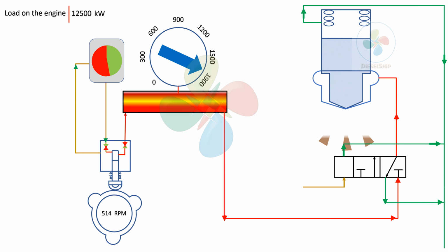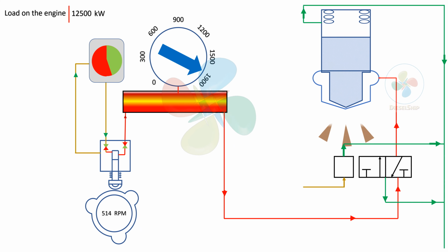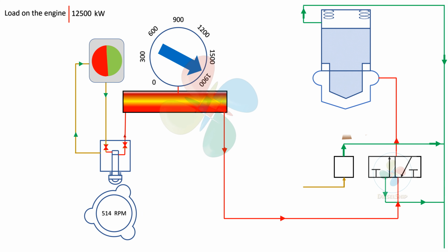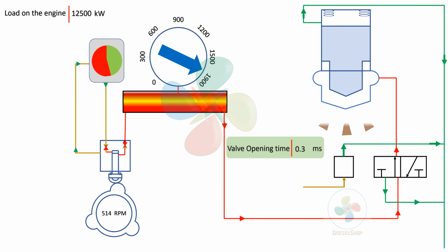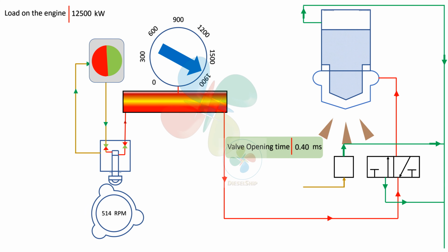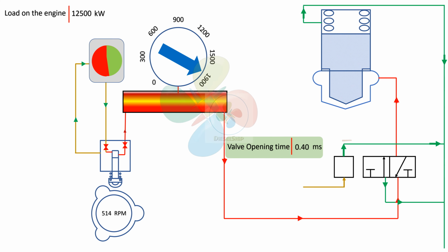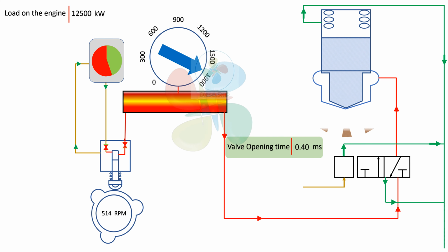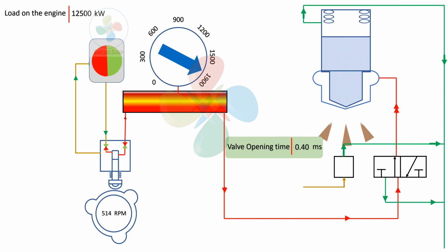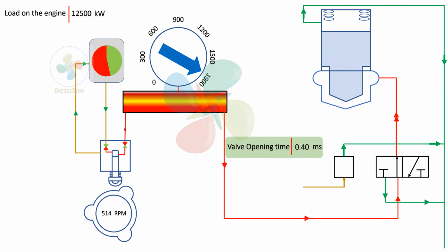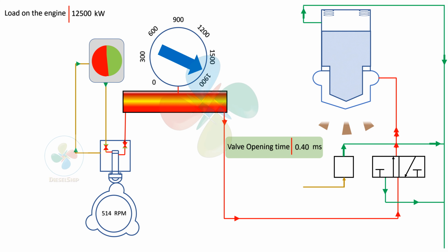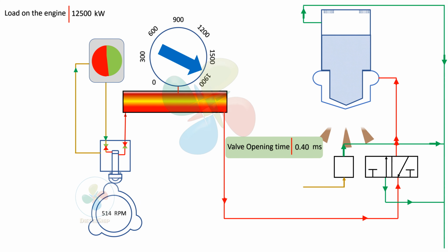What actually affects the load increase is the timing, right? The opening timing of the valve group should increase. Okay, so now from 0.30 milliseconds to 0.40 milliseconds, it has increased. It's very hard to capture because I have tried to set it up in my animation, but it's really hard to capture that small increase. See that slowly it just stops for a second. You can see I've shown a double arrow, and probably I could have shown a triple arrow as well. You can see the valve group stops for a bit more than it was doing at normal load, before the load increased.